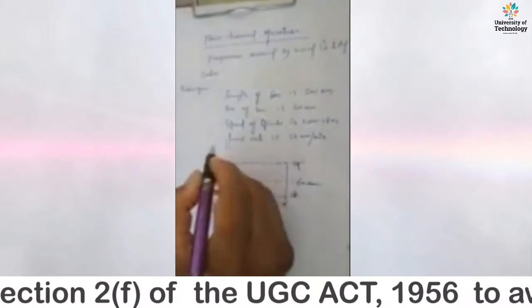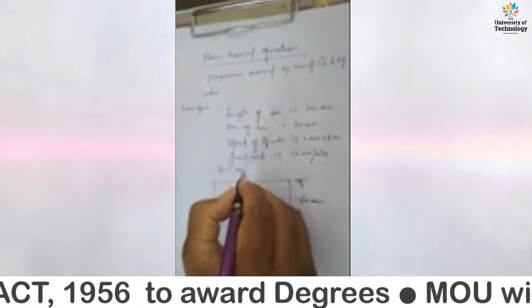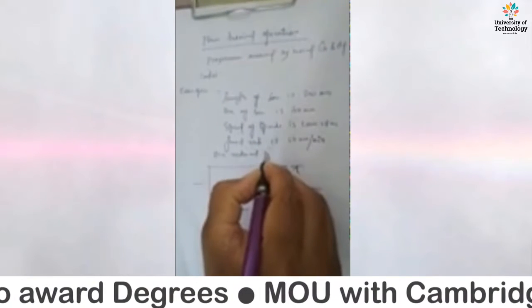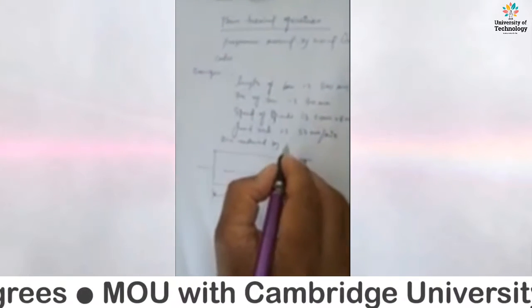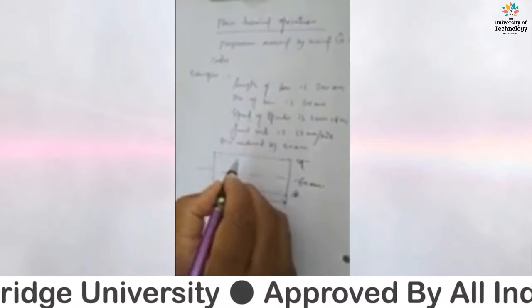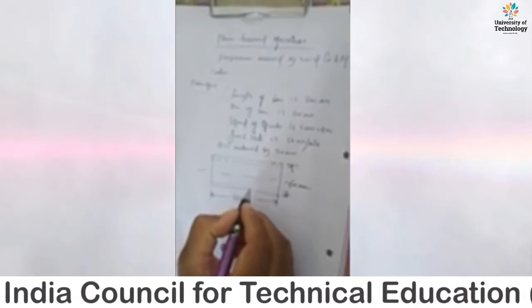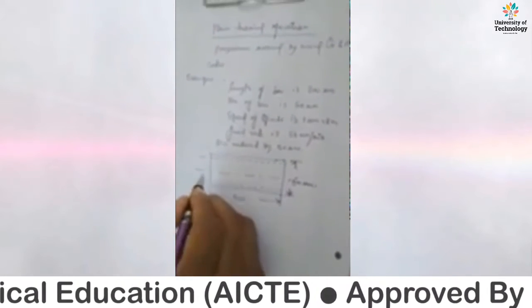The dia is reduced by plane turning operation. 20 mm represents this figure here. The dotted line represents the removing of the material. After removing this material, dia will be 40 mm.